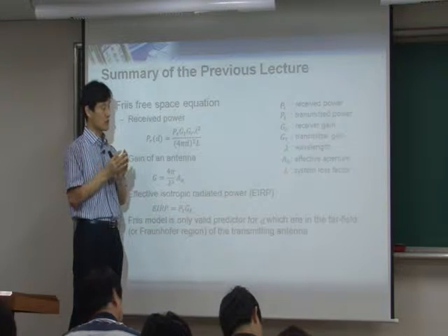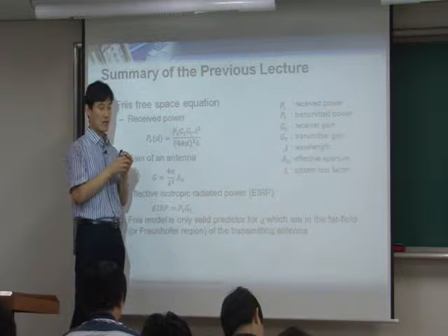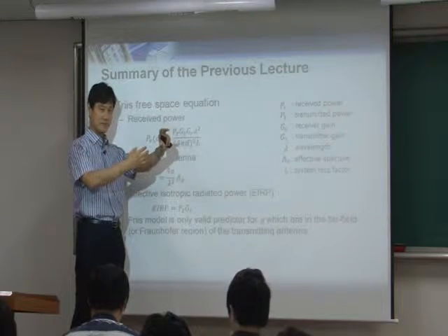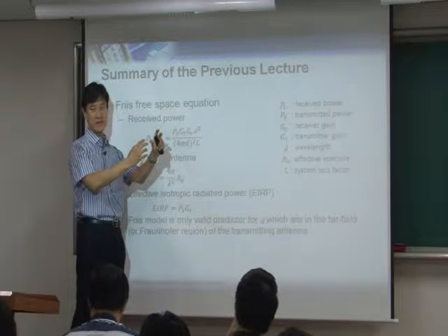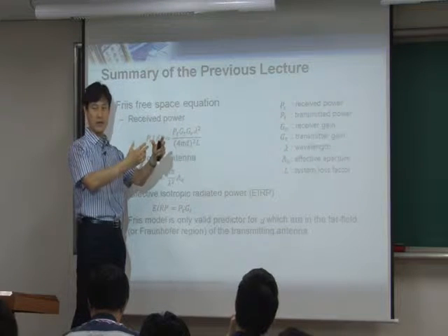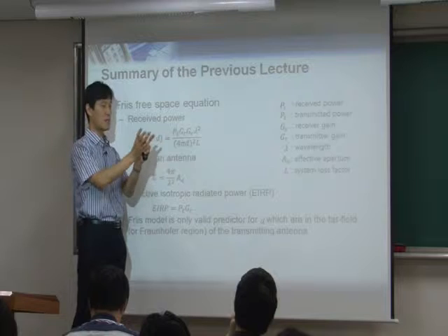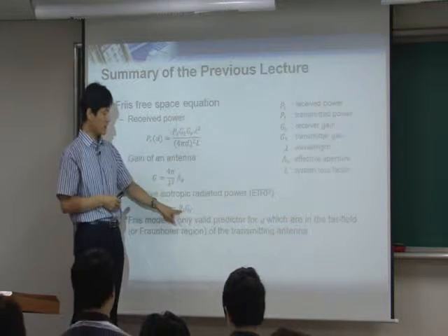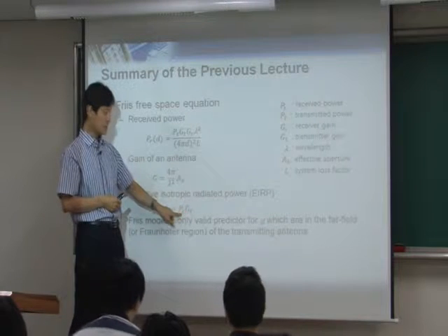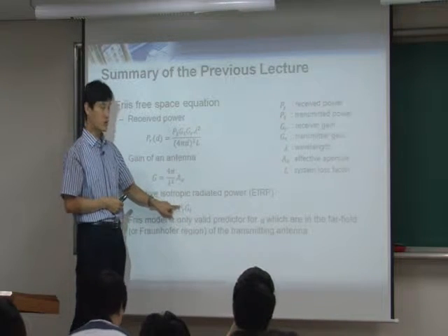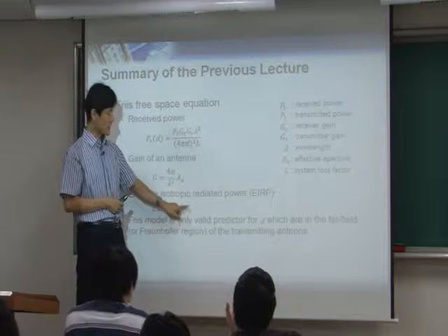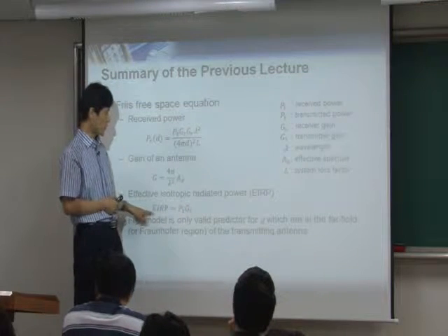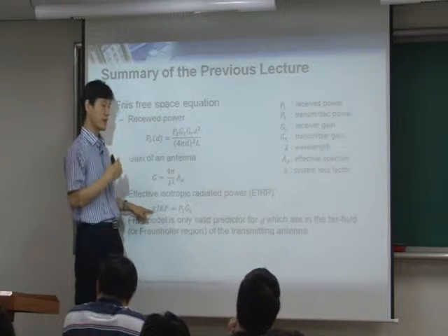But in order to transmit this much power, I use some amplifier. I use an antenna. And those devices are not ideal, right? They have their own gain. Sometimes an antenna will amplify a certain direction, okay? So depending on that gain, if you multiply that gain, this was the original power you want to transmit, but there is a certain hardware gain applied to it. You multiply that, and then that's actually what is radiated over the air, right?